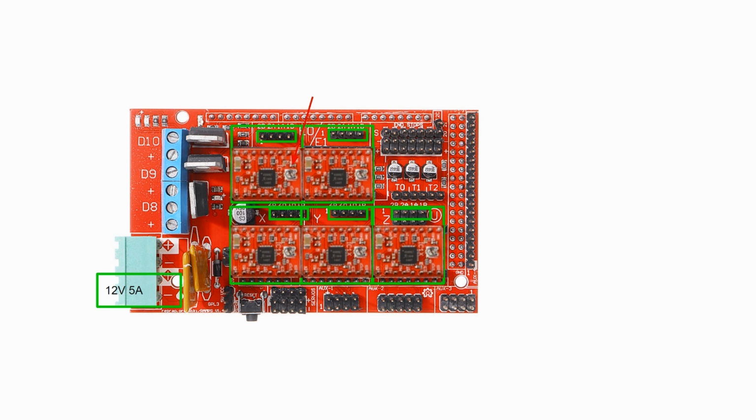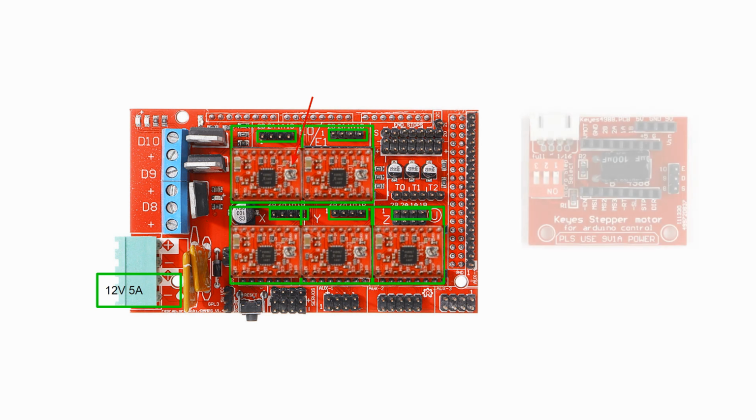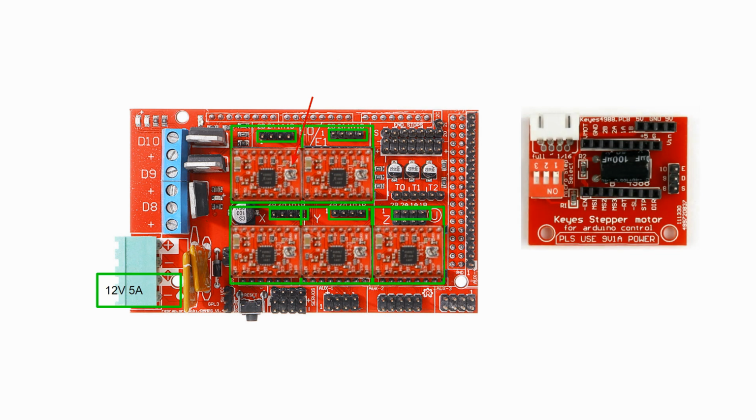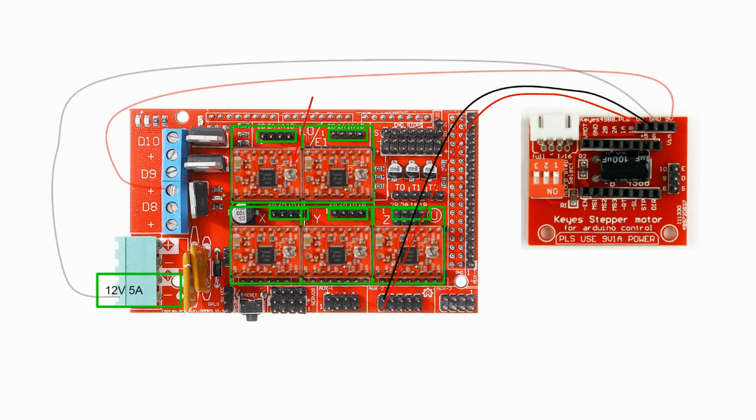Since the Rubik's Cube solver needs 6 stepper motors, we need to extend the board to connect the 6th one. First, we connect the motor control extension board to the RAMPS. We get the 5 volt power from the RAMPS AUX2 group of interfaces. We connect the 9 volt power input to the RAMPS D9 positive, which is for fan, and the ground to the RAMPS input power ground.